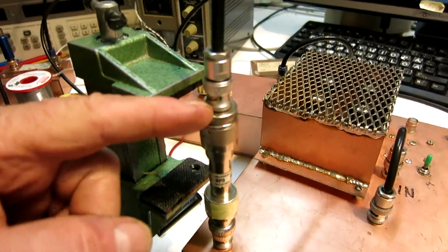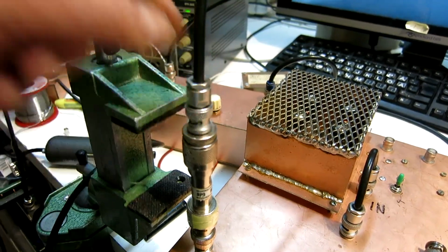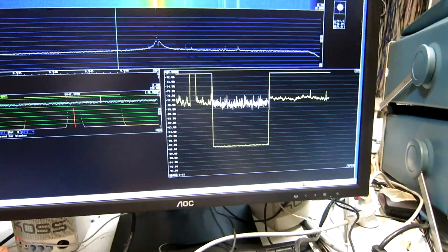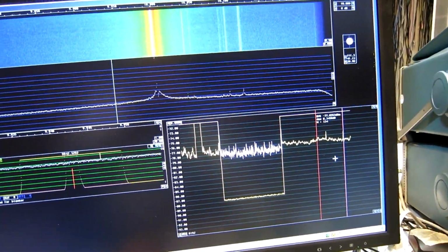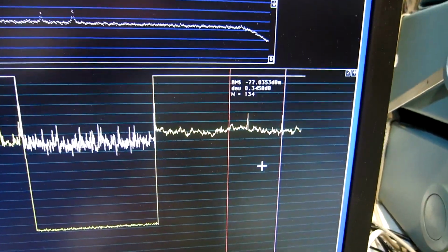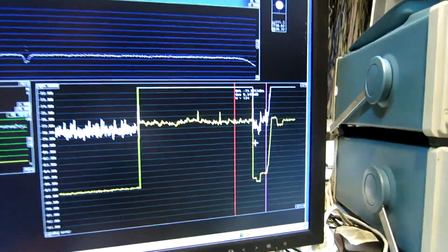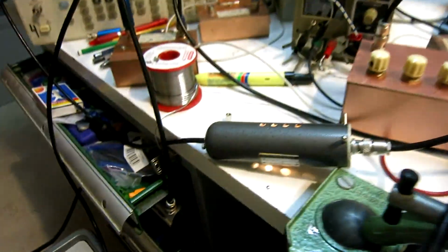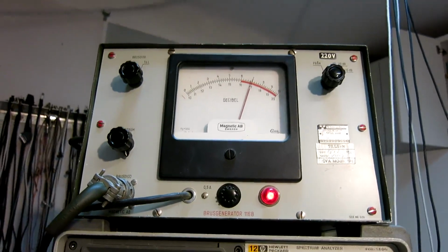With the attenuator in place, having 29.5 dBm at this point, which is the input of the notch filter, this is the noise floor I'm observing. Something like -77 on the Linrad scale here. I have not calibrated it at all. To get the same noise level with the noise source, this one, I have to put it to 17 dB.